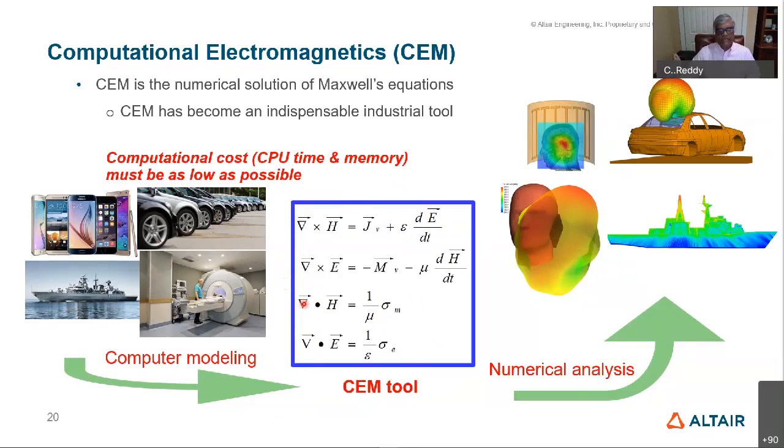So each discretization part is where you can impose your boundary conditions on the electric and magnetic fields, so that you'll be able to solve for those quantities, and then of course add them up over the object, so you can have the currents, the fields, anything you like to have for an antenna available to you.